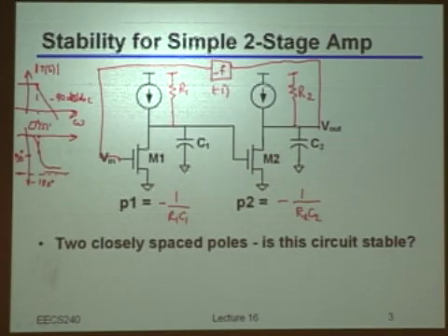So theoretically, but really, really theoretically, you will always have a positive phase margin here. You never hit minus 180. So mathematically speaking, if this is the real model, if this is the reality, that should not oscillate. So it should be stable. But that's actually the tricky question.